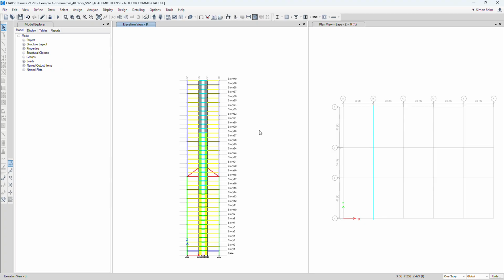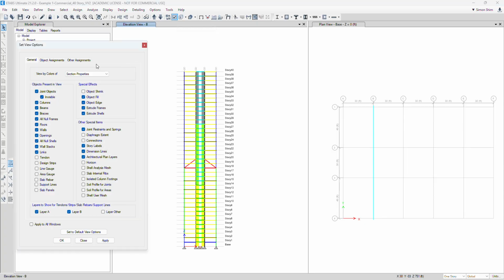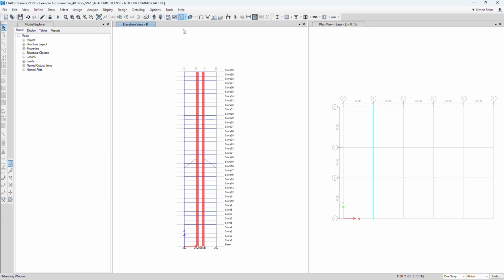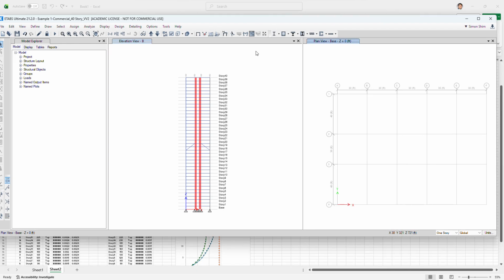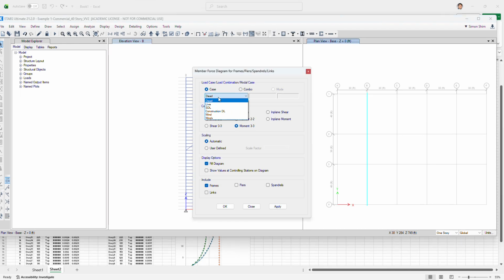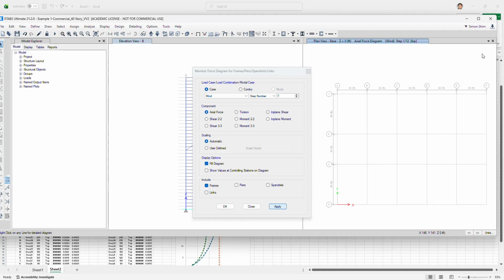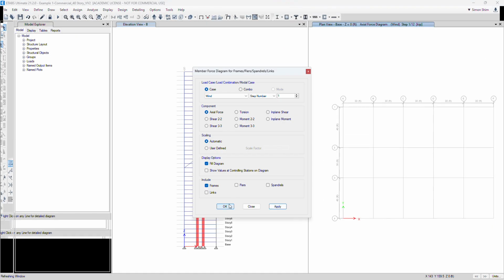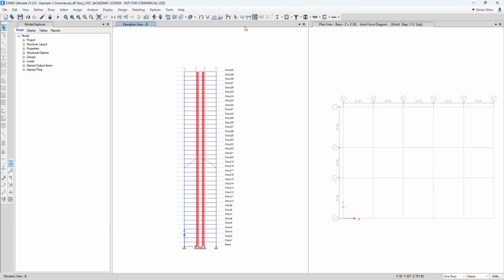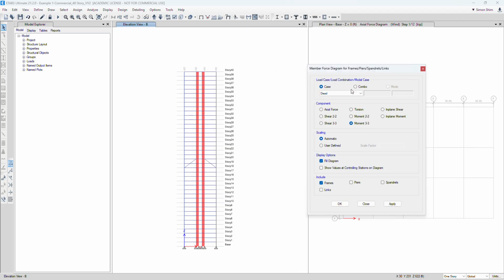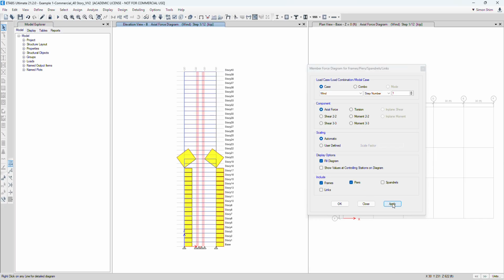All right, so this is the outrigger model because we already have it. I'm going to turn on the extrusion. All right, so let's take a look at the axial force. Wind is blowing left and right, right? We've looked at this many times. This time, wind x ultimate axial force.